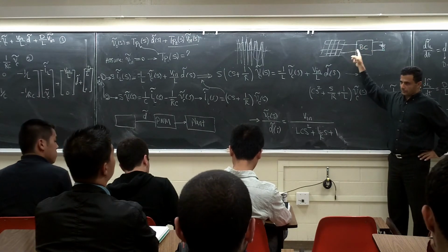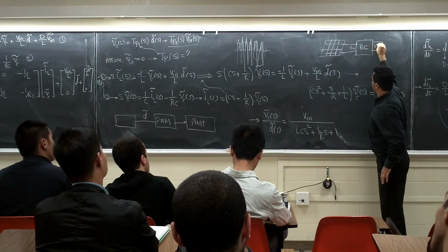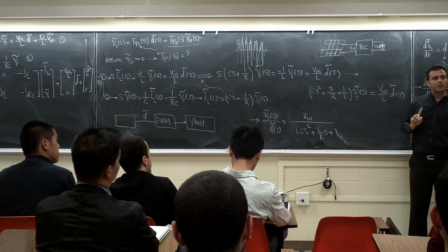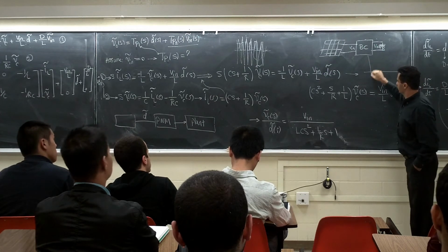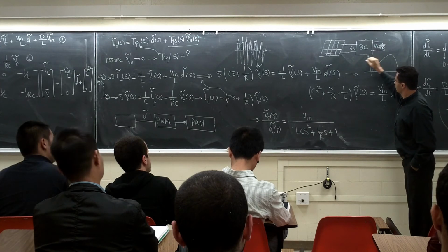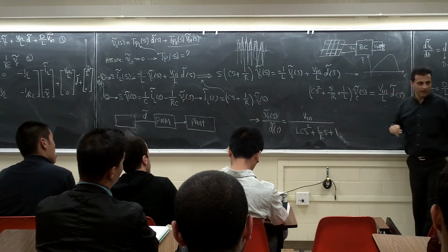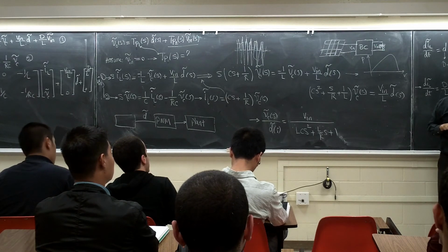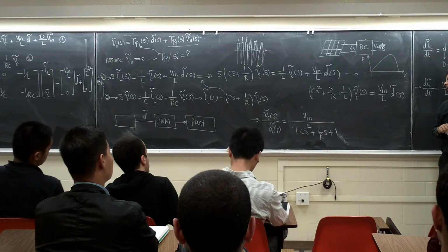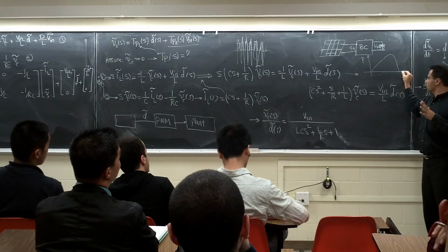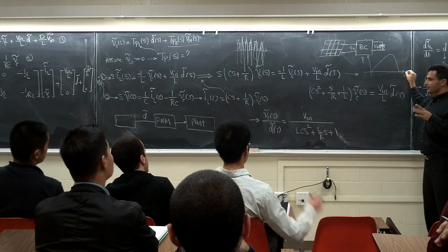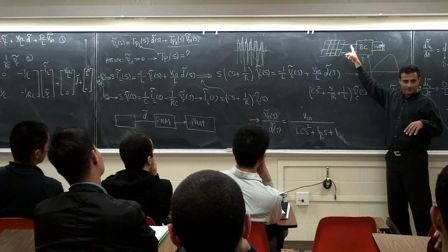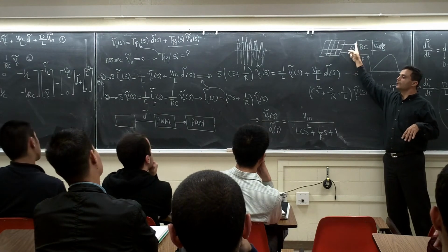In the solar panel, so this is V in, this is V out, right? So when you do the MPPT, what you are controlling? What parameter you are changing? You want to control this voltage, right? You don't want to control this voltage anymore, right? You want to control this voltage. With what? With what?